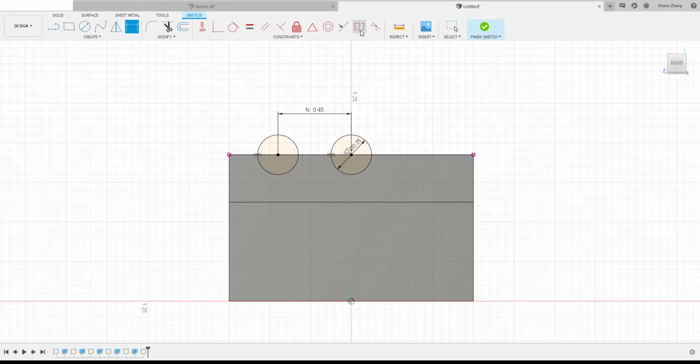So let's try it if we can do it. So we can use X, Y, Z to mirror it. I hope. So we're gonna mirror this circle, and so you're gonna first pick what you want to mirror, then mirror the line. I have to click here. So now I'm picking up the center line. Center line, if I look at the cube here, the vertical line is the y-axis. So that means the center is the y-axis. I'll try to pick y. So it does pick that.